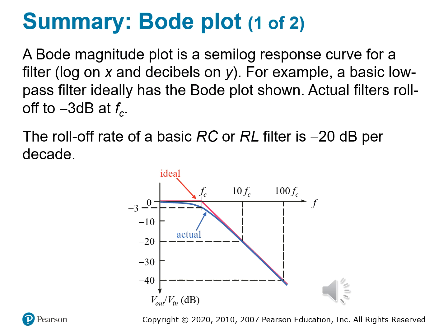You have a classic roll-off rate for an RC or an RL filter. If you didn't know what that was, a classic roll-off rate is negative 20 dB per decade. So that's how many dB is decaying per decade. Right? Every time the frequency increases by a factor of 10, the gain drops by 20 decibels.